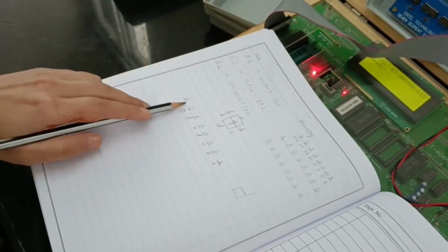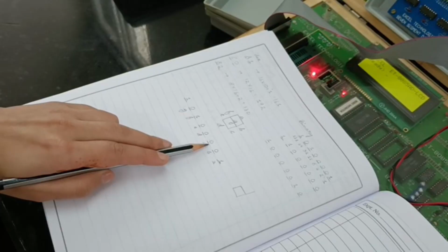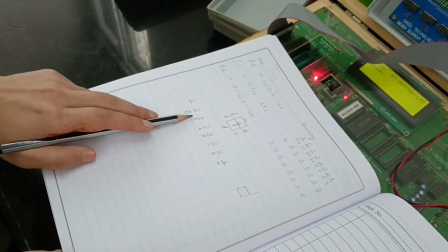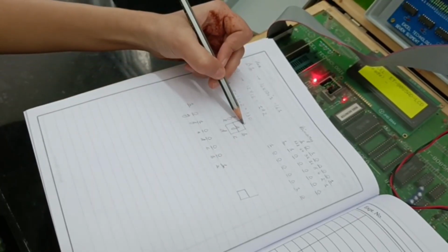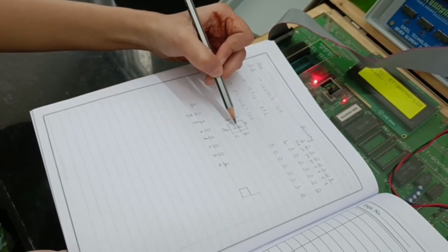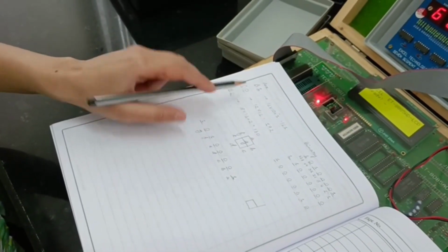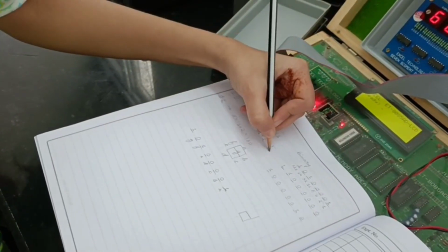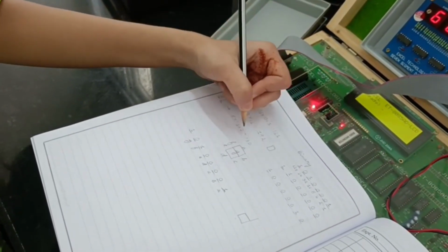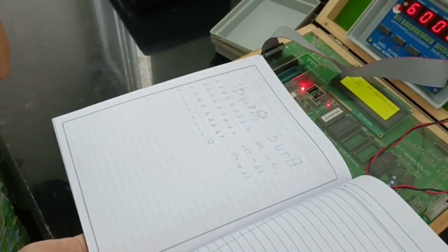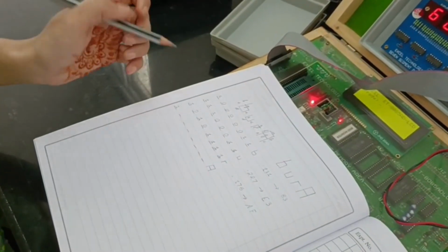So when I wrote this 10100001, A and F are turned off, rest all are turned on. So if you turn off A and F, then you get D. Similarly, C0 corresponds to O, and 82 corresponds to G. Now I tried out some other letters when I realized this logic.